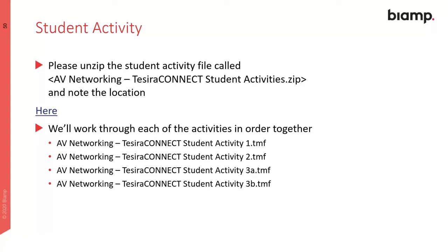Right. AVB can handle more channels, 128. Dante's maximum chip, I think, can handle 64 channels. I think there are newer iterations, but of course, as the number of channels goes up, your cost increases quite significantly. Exactly. Just as an example, our Dante card, which does 64 by 64, is more expensive than our AVB card, which does 256 by 256. Exactly. Was it 240 or 256? I forget. Sorry.